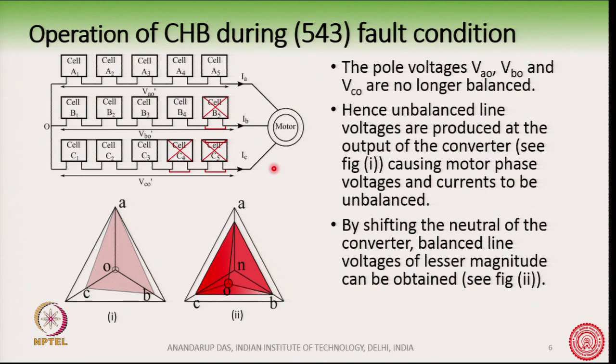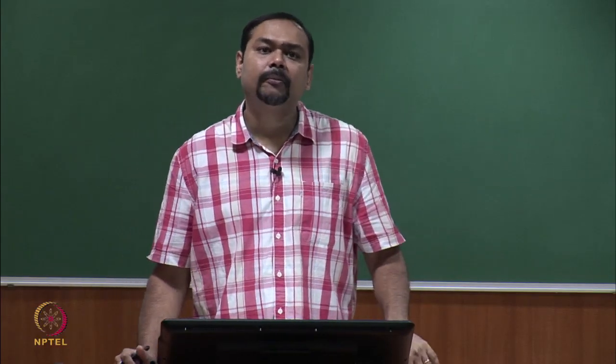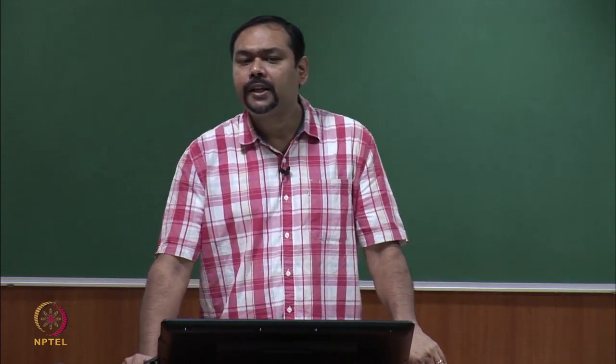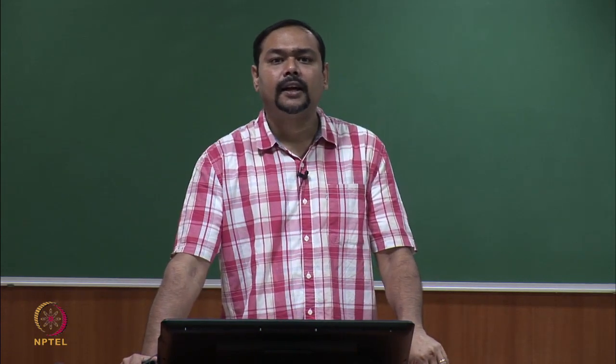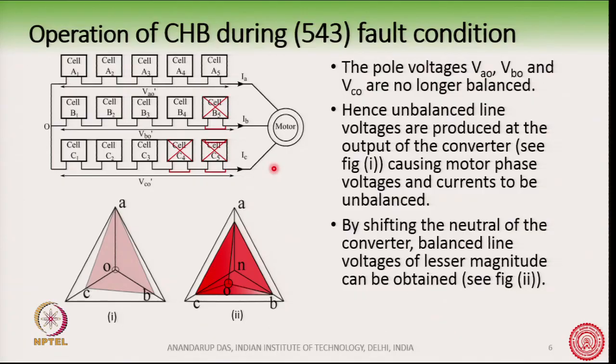As soon as the line voltages become balanced, the motor phase voltage will also become balanced and balanced current will flow. So, the load will never understand that there has been a fault inside the converter, as long as we can ensure that the line voltages are balanced at the output of the converter.